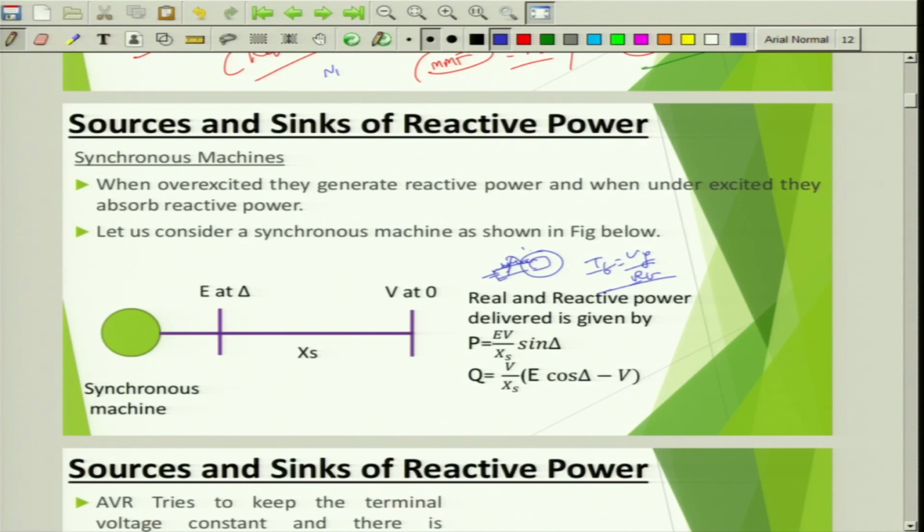Henceforth, if more inductive loads are coming up, then to maintain the voltage profile at the nominal value, they would increase the current or reduce the resistance in the field circuit, and the other way around. If let us imagine there is a high capacitive load or the Ferranti effect or whatever reasons, then you need to reduce the current by increasing the resistance at the field side, and everything depends upon these expressions.